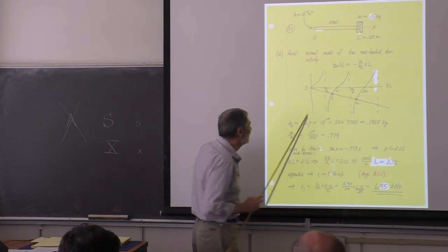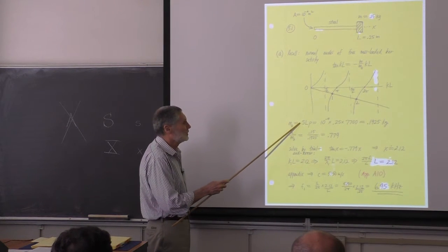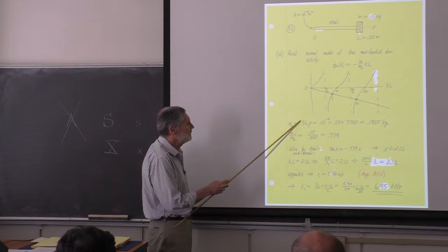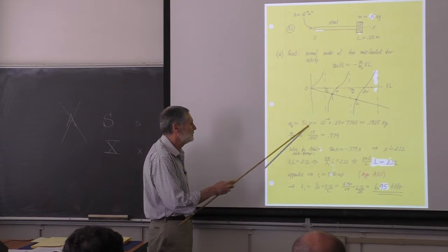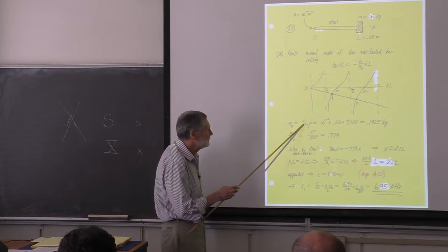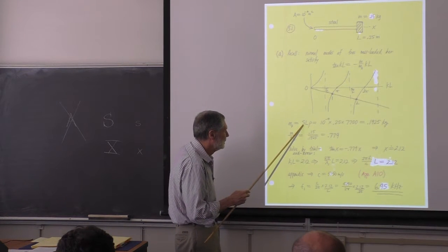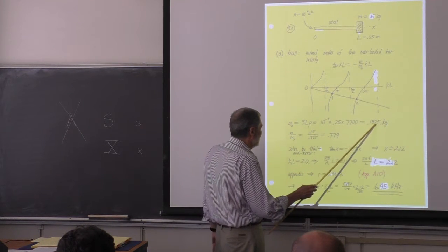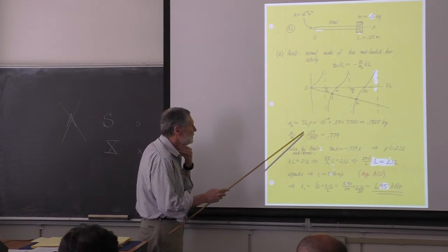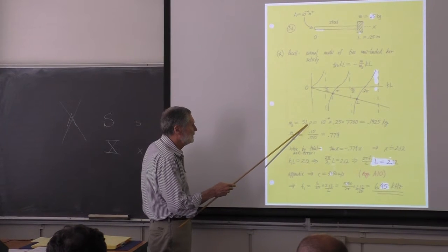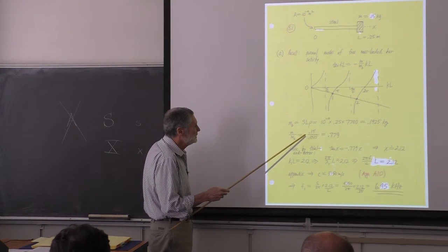That's what's relevant. What's the mass of the bar? It's the volume of the bar, the cross-sectional area times the length, times the mass per unit volume, which we call the density, right? So this is going to give you the mass of the bar, and it's equal to this. Oh, I've gone to the appendix to look up the density of steel.